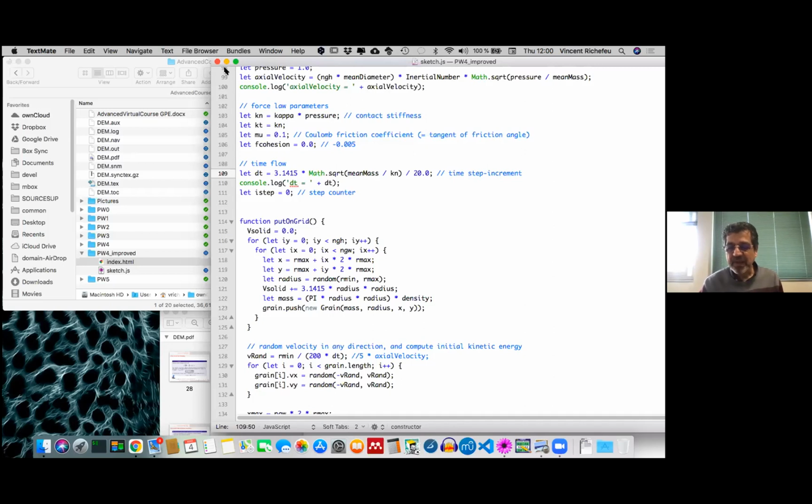So typically, if you model a concrete with cohesive bonds, the elasticity will matter a lot. So the question may appear in this case, but if you are dealing with a granular material which is not cohesive, like a liquid, I think this is not a question. You can choose 0.8 or 1, it will be okay.